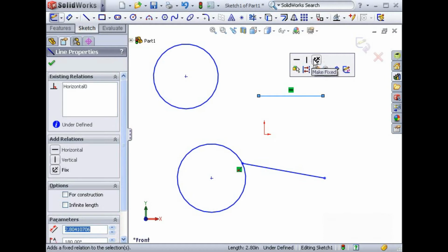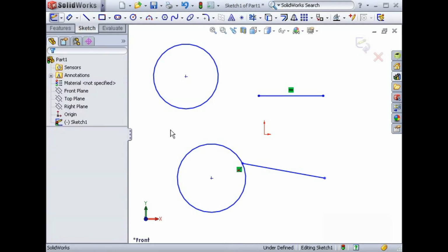If you're new to SolidWorks and geometric relations, I would suggest using the Property Manager. This way you can see the name of the relation next to each icon. Once you get more familiar with geometric relations, you might find it faster to use the pop-up toolbar instead. The options you see in the Property Manager and the pop-up toolbar depend on the geometry you select.